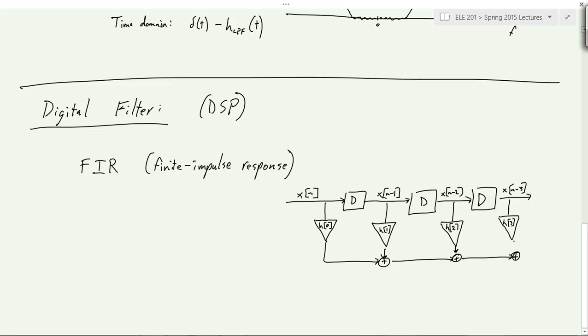I know we don't use block diagram notation that much in this class, but I expect it's pretty straightforward what this means. The processor is going to take these different stored values, do this multiplication, add them together, and use that to produce y[n]. So at each time n, it's sort of averaging the past few samples of x. We can see that this is a convolution, a linear time invariant process.